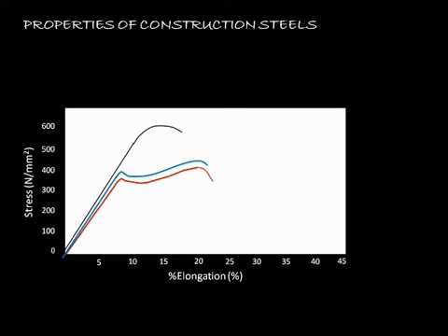Grade 304 stainless steel has a much lower limit of proportionality. The stress-strain curve departs from linearity at a much lower stress. However, the curve exhibits extremely ductile behavior, and although there is a large non-linear portion to the curve, the ultimate tensile stress reaches a similar value to S275 and S355 steels. After the ultimate tensile stress, there is still some further ductility to the curve.